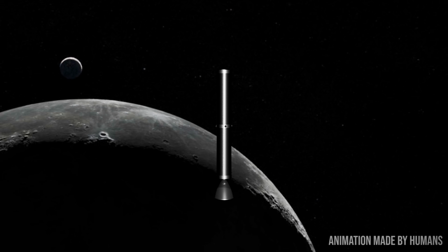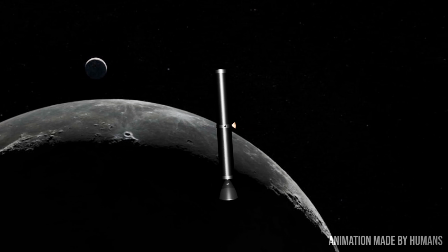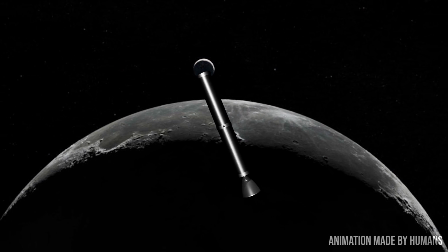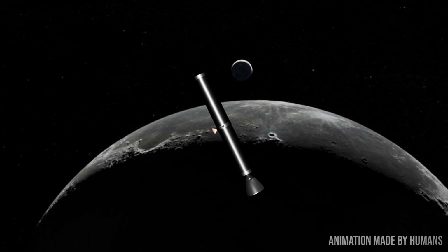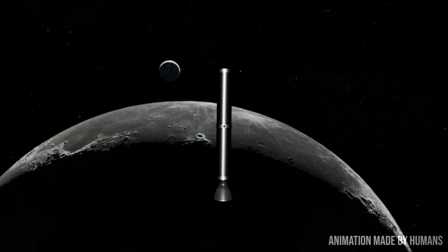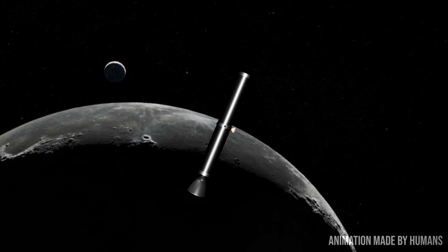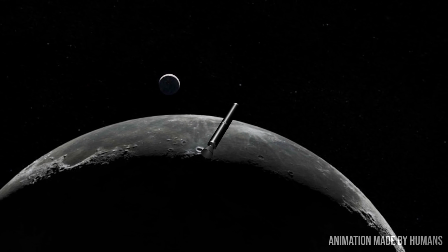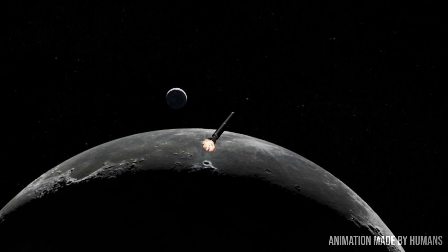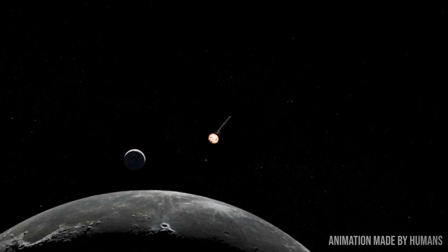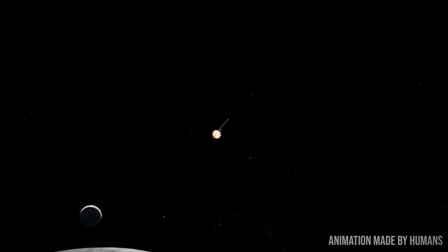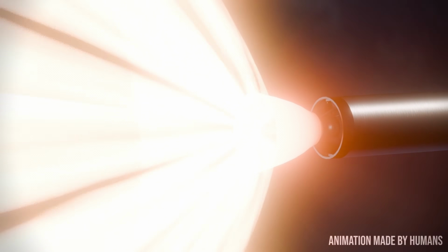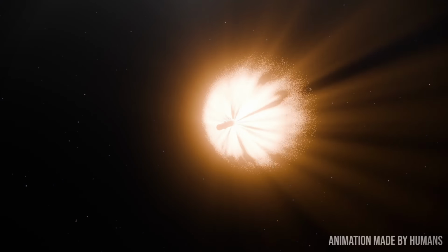First, the need for controlled payloads, what we might call mass driver rockets or rocket pods. With a mass driver, you cannot just shoot dumb rocks into space and expect them to arrive anywhere in a circular, stable, aligned orbit. Real payloads have to do cleanup work, raise periapsis and circularize, correct attitude and navigation errors, and make whatever small plane and timing adjustments are needed, because a surface launch can only put you on an initial trajectory, not deliver a final operational orbit by itself. In other words, every payload needs a rocket thruster capable of performing the careful maneuvering required to reach and rendezvous in low Earth orbit, regardless of the initial orbital conditions.